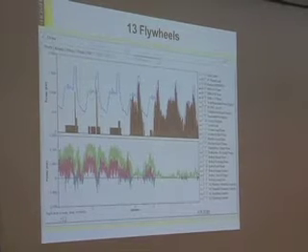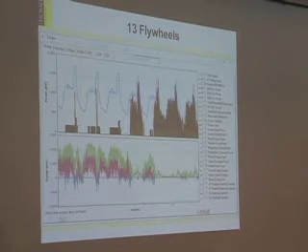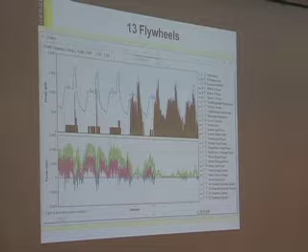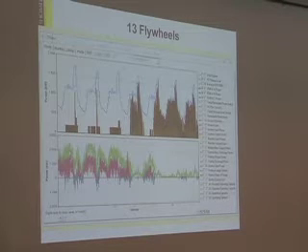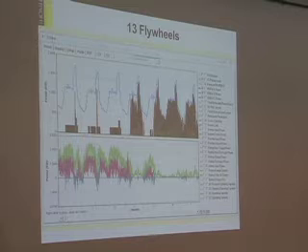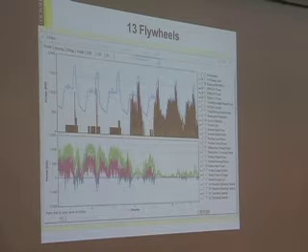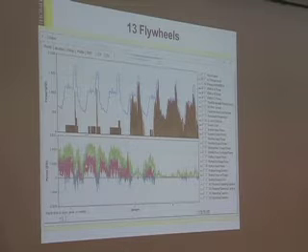So this is 7 days. This is an analysis we did with 1 minute time steps, actually. And we have 3 generators. And you can see, I've got to get these colors right. Right, so this green color is the wind turbine output here. The red is the excess energy, or we call it excess. We used to call it dump. That's even worse. We should probably call it secondary load, except that you may not have a secondary load, in which case it really is excess. Whatever.